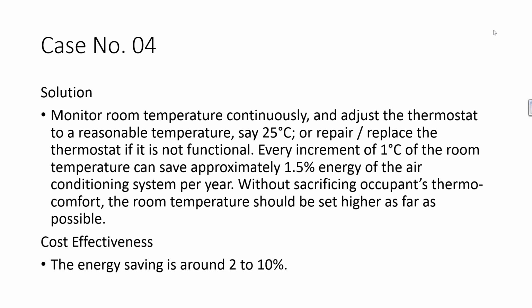The solution for this: monitor room temperature continuously and adjust the thermostat to a reasonable temperature, say 25 degrees Celsius, or replace the thermostat if it is not functional.